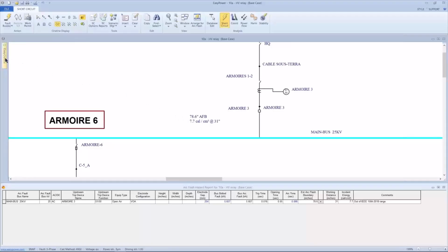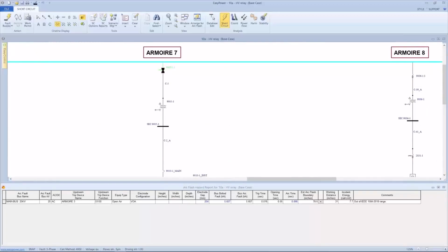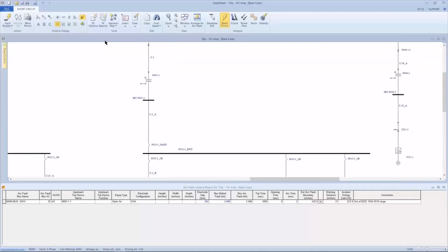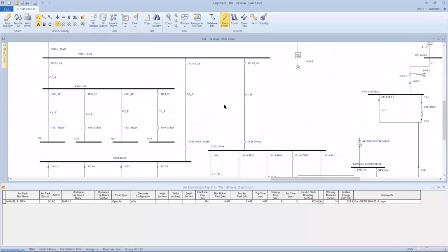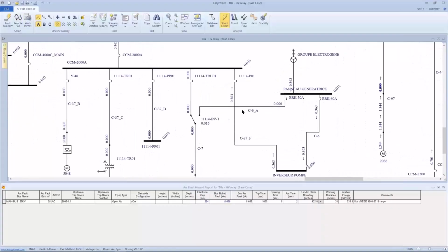So if I trace back upstream from that breaker, or from this fuse switch, I notice that the current is being supplied by a generator of some sort. And sure enough, here's a generator that's on an ATS, but it has back feeding into my bus. If I look at my remote voltage from a single bus fault, I can see I have a continuous supply of 360 amps out of my generator. So making that correction solves the problem. I thought that was kind of fun, unique.